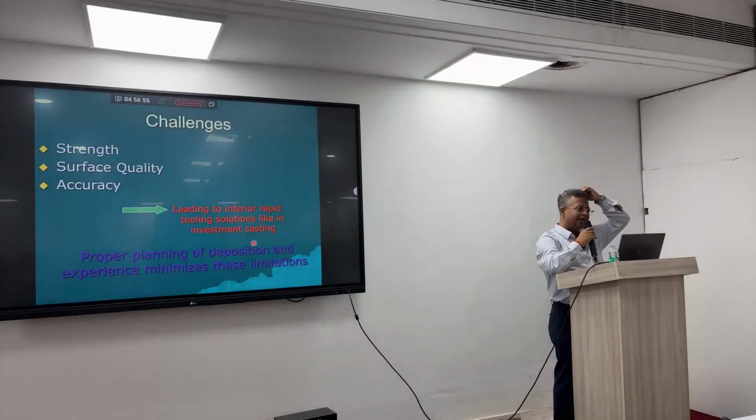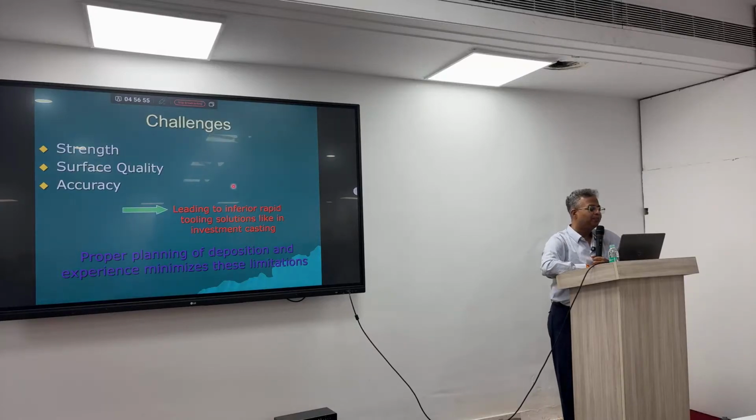Still, if you look at the challenges, the strength may not be as high as in any molding or compression molding in the case of plastics. But definitely you can enhance it by proper planning, by optimizing parameters, or by blending certain additives or fillers or making composites.